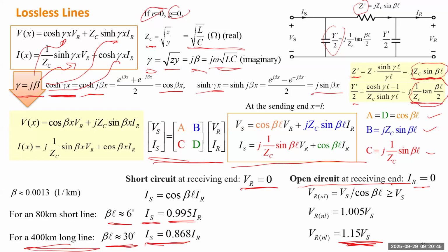So that can trigger some overvoltage protection, because usually we expect the transmission line to operate within roughly a 5% violation. So if you operate 500 kV lines, you want to maintain the voltage everywhere within the range of 475 to 525, roughly 5% violation. But 15% is too high and will trigger some protection.